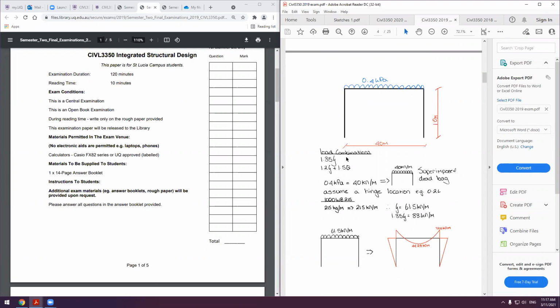I know I probably told you this before, in my concrete exam, back when I was a little second year in 2017, I took my bending moment on the wrong side of my diagram. So I had something like 400 kilonewton meters instead of 150 kilonewton meters because I took the compression instead of the tension side of the graph. With all my working out, I needed something like 6 N36 bars in something that wasn't going to fit. I had 5 minutes to go. I realized what I had done, and I wrote a note about the mistake. I have made this mistake. I'm fully aware I've made this mistake. And it just allowed her to know exactly what I had done, and I got carried through marks.